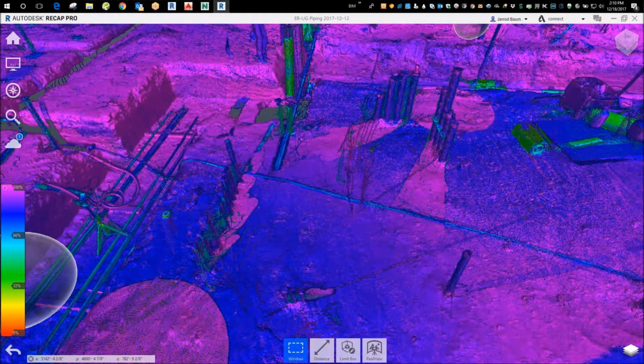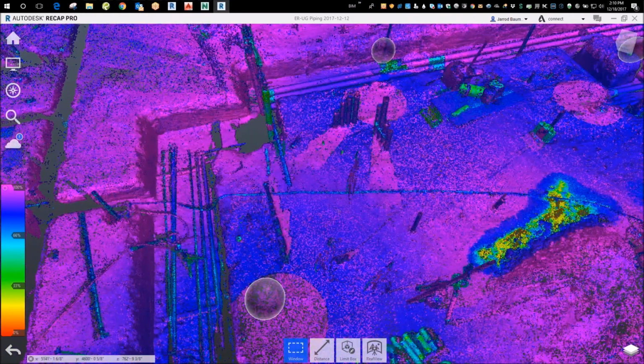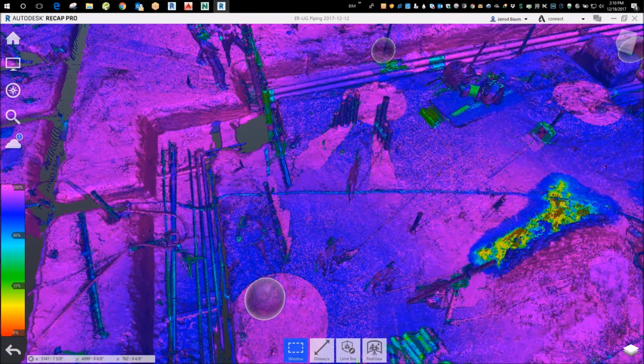We can see that quickly. So what we're going to do is use CAD files, Revit models, Navisworks NWCs, and this laser scan, and lay them all together precisely with the civil coordinate system in Navis, so that you guys can see how you can section it down and use it just like a Navis clash model, to say, hey, see these conduits?